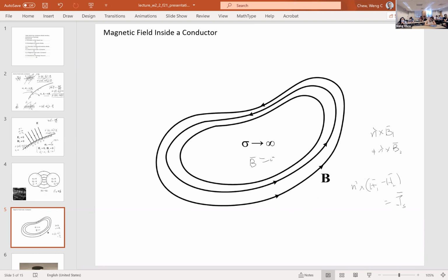Okay? So the only way is to have eddy currents being produced. Any questions regarding the shielding of magnetic field? So shielding of magnetic field is not that simple. You need good conductors. So you can't shield out low frequency magnetic field very easily.